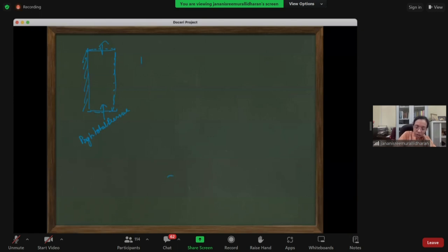So what you're essentially saying is P naught is equal to P minus half rho U square minus rho g delta h, where h is your current height minus h reference. So you're adding this hydrostatic component. Where do you remember this hydrostatic component from? It had gone into the equation for the Boussinesq, right?